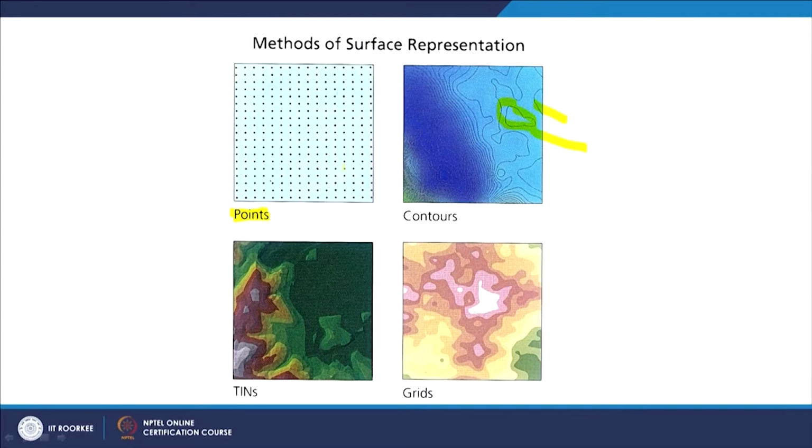Using the same point data, we can create a TIN like here, and again using the same point data I can also create a grid, that is raster. Now, using this grid, as we have just discussed, we can also create contours. That means the contours can be created by two methods: directly from point to polyline, or from surface to polyline.